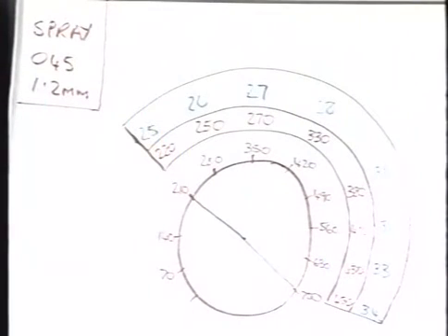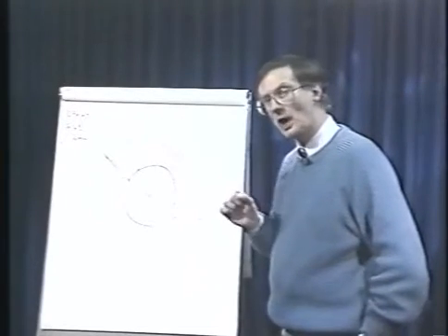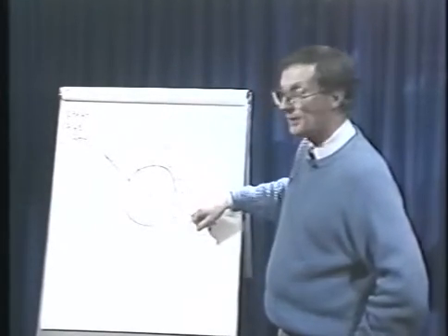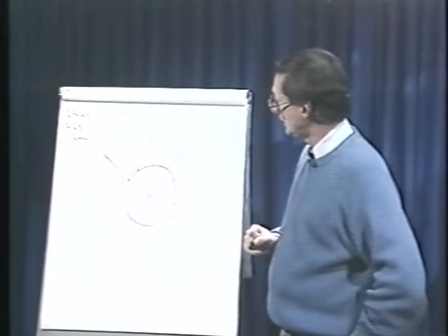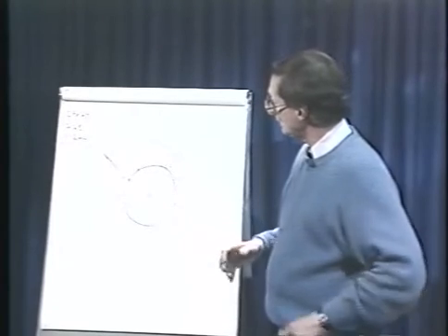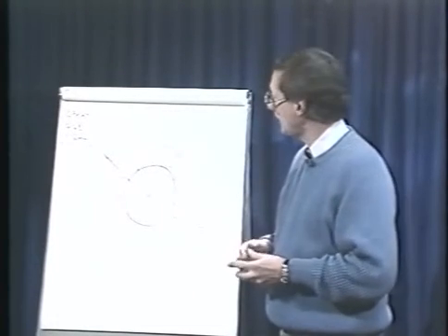As you can see, the wire feed range now is extended from the 10 o'clock position to the 5 o'clock position. The current, we need at least 220 amps, a lower voltage, 25 up to 34 volts. 045 is the most suitable wire, not only because it's a lower cost wire than the 035, but also because of this extended current range and the achieved deposition rates. In the current range of 220 to 450 amps, we can achieve almost up to about 19 pounds per hour.